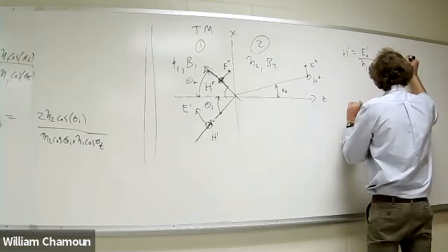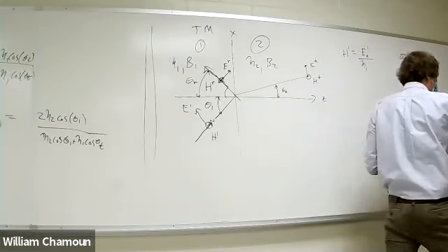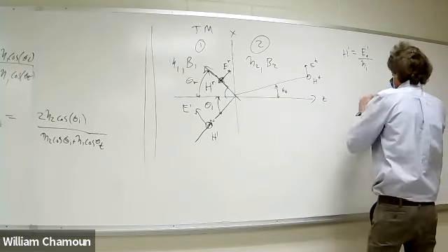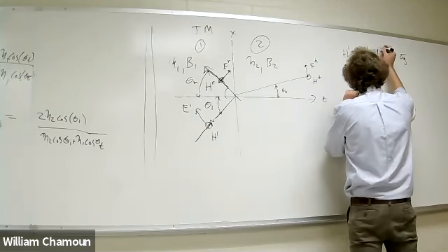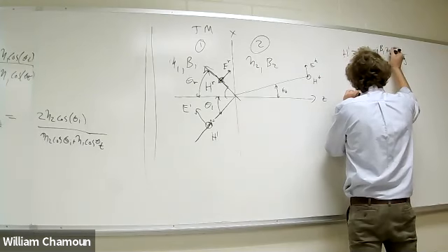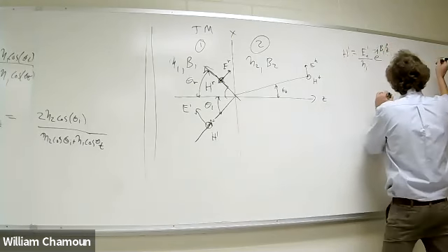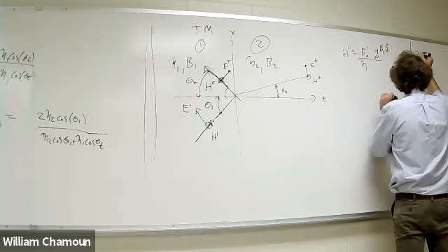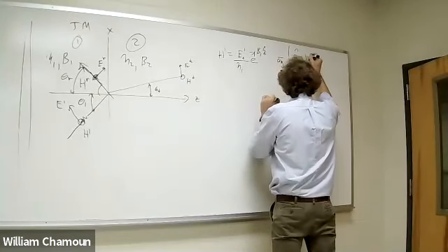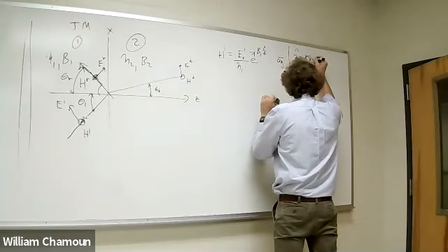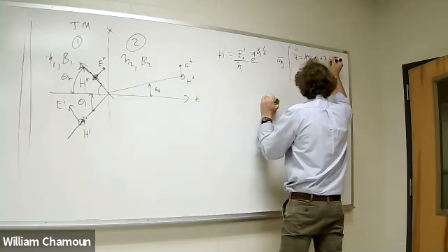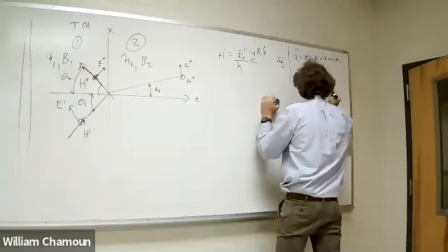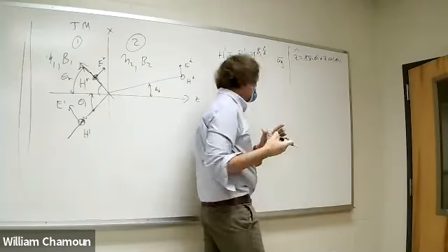So I put that out here. Show you how we set this thing up. All right. Now this is going to propagate. So it will have e to the minus j beta 1, just as before. And z prime is actually equal to x times the sine of theta incident plus z cosine theta incident. And that's just as before.